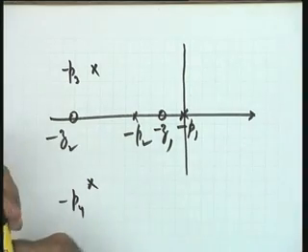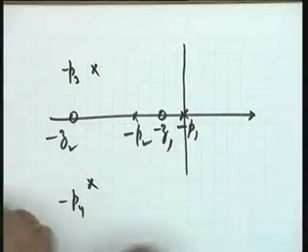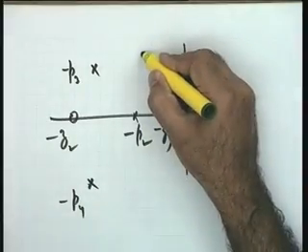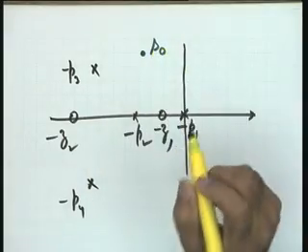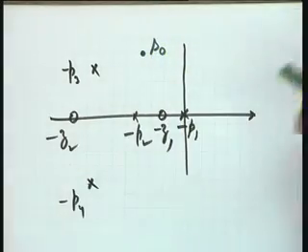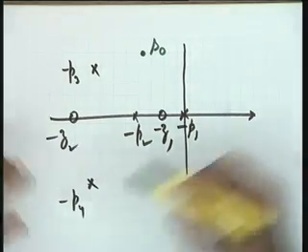I am making it very clear that I am making reference to the function F(s), and I have to scan the total S plane. So let me take this as the trial point. The trial point is s0. I want to see whether this point satisfies the angle criterion. If yes, it is a root locus point, because there will be an associated value of k.